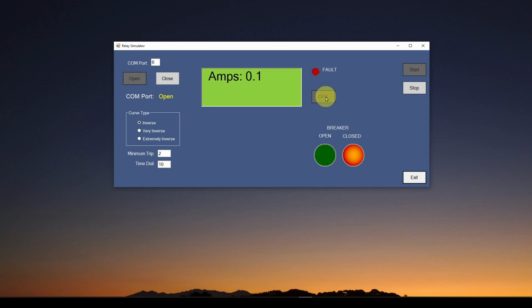That's really important because if this does trip, you're going to want to go back and troubleshoot why it happened. It's really nice in the real world to have a chart showing current versus time, so you can understand whether it was a whole lot of current for a short time or what. That'll help you figure out what happened in your circuit.